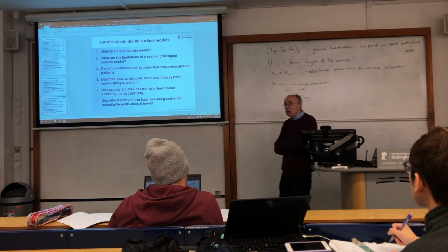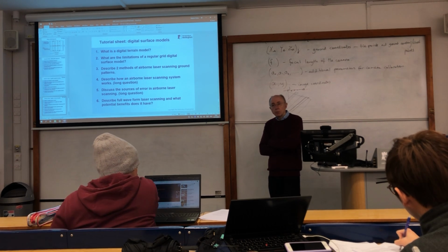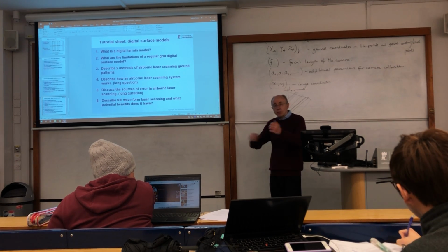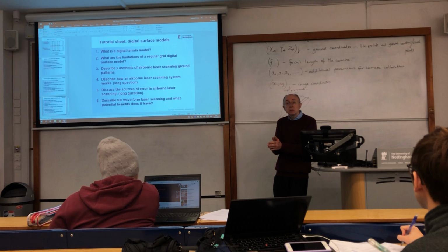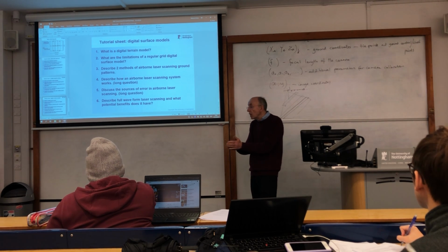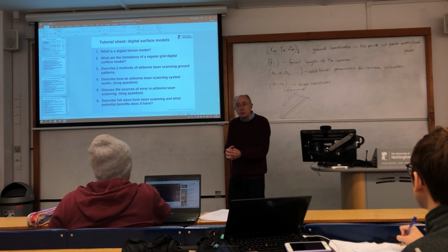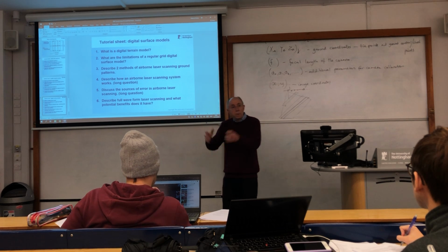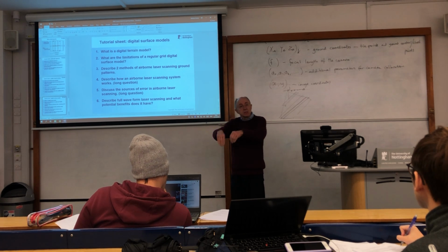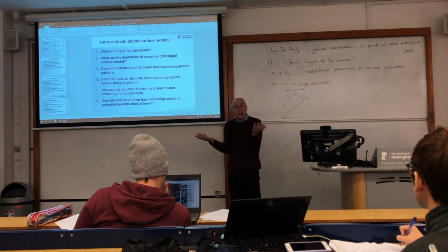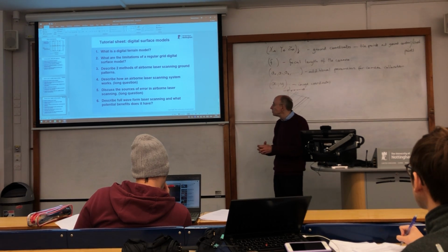I suppose the biggest limitation is what grid interval you use to best define the landscape where you're working. Do you have a 50-metre grid interval, or a 10-metre grid interval, or a 1-metre grid interval, or 5-centimetre grid interval? Because the bigger the grid interval, the less data you're going to collect. So from an efficiency point of view, from a processing point of view, it's an advantage. But, of course, fine detail will fall inside the grid, and you won't capture it, you lose it. So the limitations are the grid size.